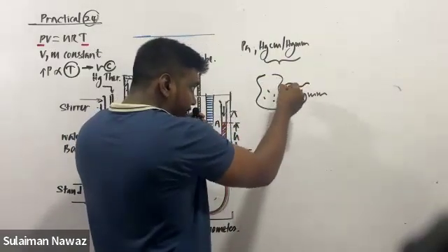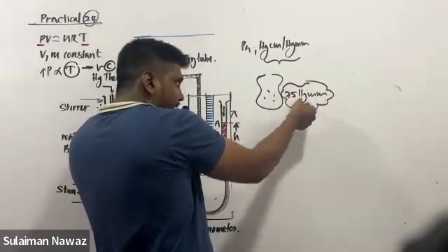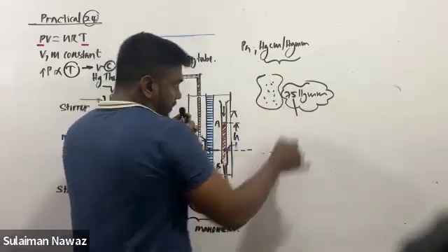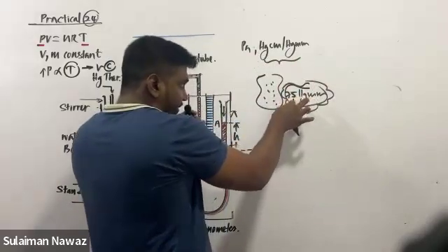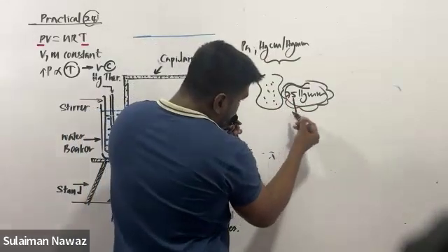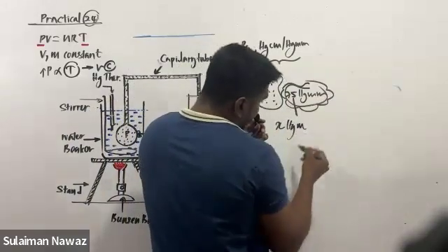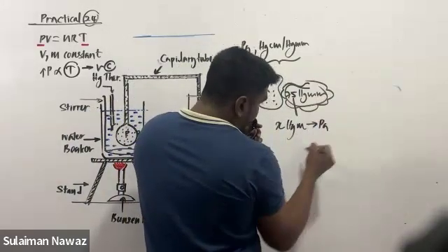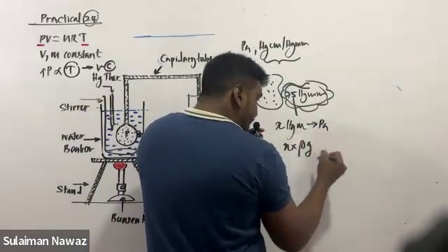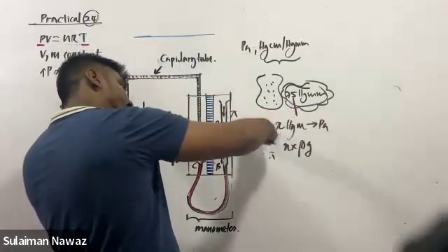Mercury millimeter seems like a length, but actually it measures the pressure of the gas. If you want to convert mercury millimeters into Pascal, you multiply by the density of mercury and gravitational acceleration.